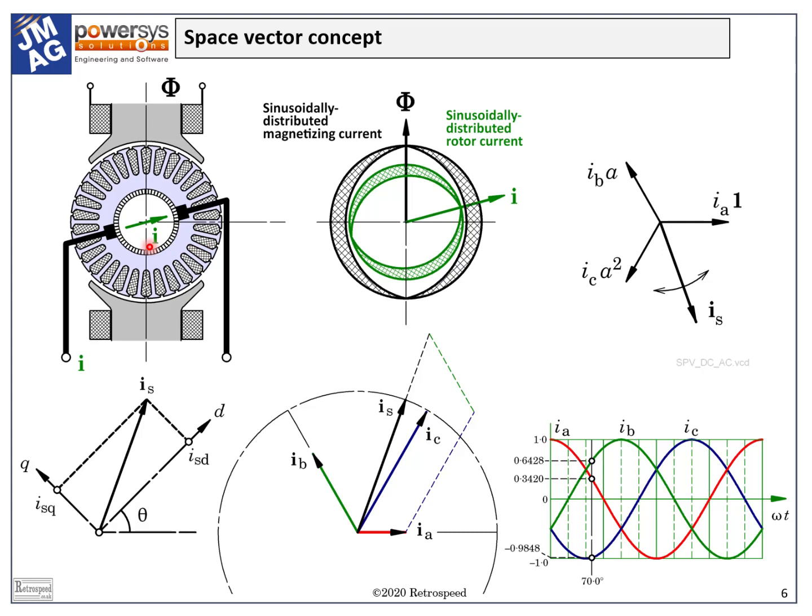The pattern of ampere conductors which establishes the armature reaction flux has a fixed shape or spatial distribution, but once that distribution is given, we can focus on just two parameters that define its main effects: the magnitude I in amperes and the direction, which is determined by the angular position of the brushes.